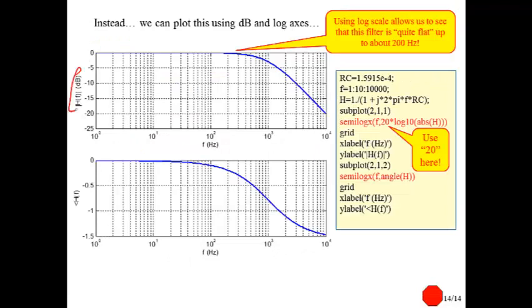So now we're plotting dB on a log frequency axis. And now we see that, remember, 0 dB is absolute 1. So this is our nice pass band, and it's staying so beautifully flat all the way up to beyond 100 hertz, and up to 1,000 hertz we've dropped down to 3 dB.